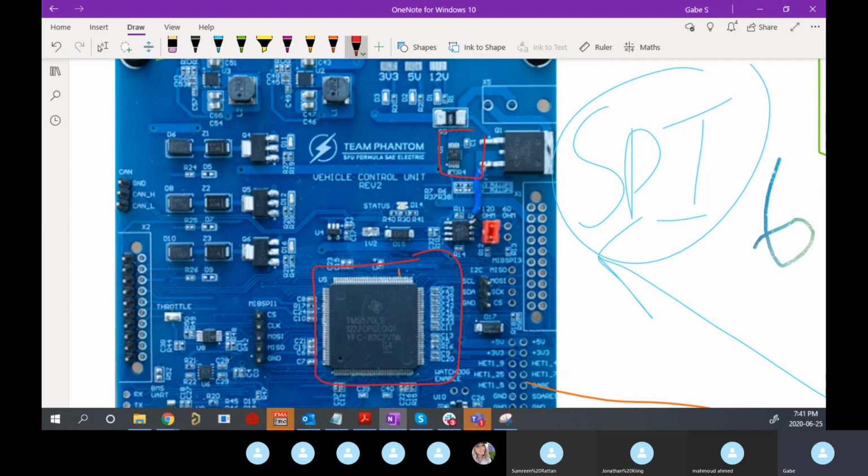And what it does, 12 volts comes in through here, and there's a shunt resistor we call. So this resistor is meant to handle all the current coming in. That's why it's so fat. So it can do about 1 watt, I think, of power. And it's 1 milliohm. You can imagine if all your power flowed through something that was like a kilo ohm, you'd burn a lot of energy through I squared R, right? So really tiny resistance to try not burn energy.